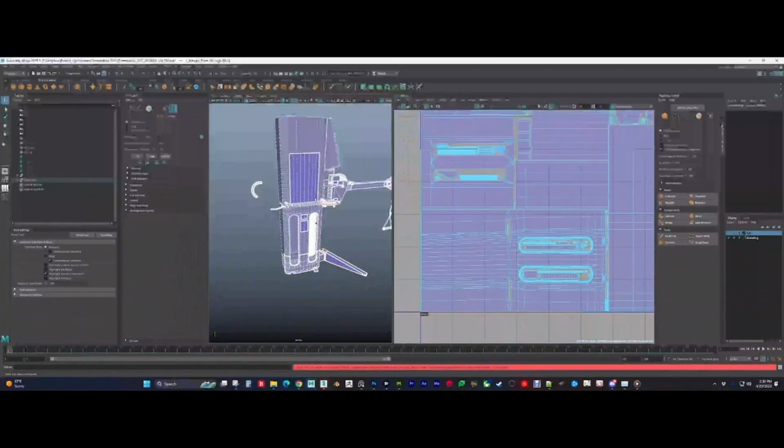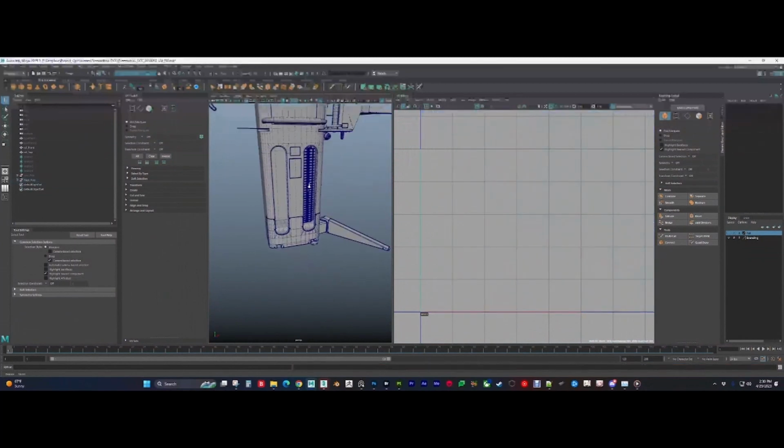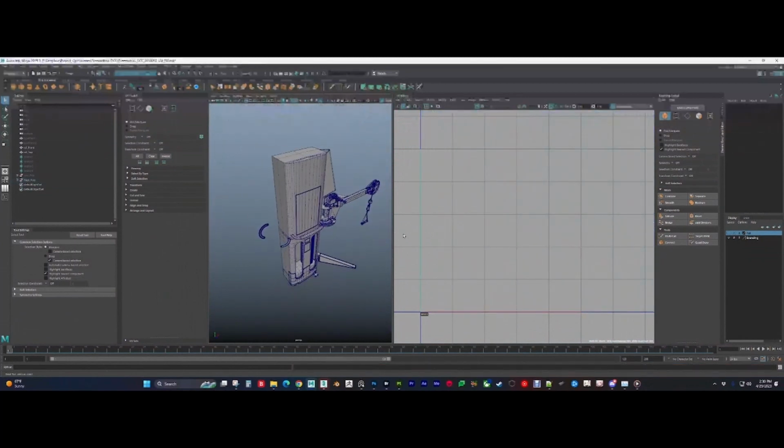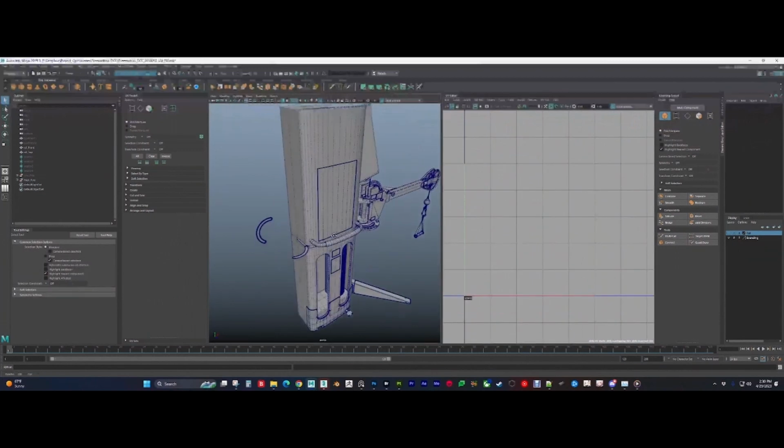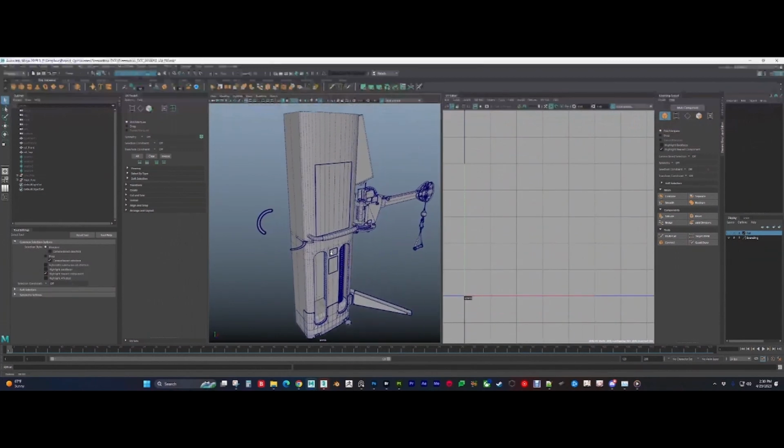And then going off into what I like to do, I use Substance Painter for my texture painting. In Substance Painter, I don't know if you noticed, but inside of the Baker, there's an option for your high poly and your low poly, and it uses a suffix, underscore low, underscore high. So I go through my model and apply the underscore low suffix to my low poly. I just want to show you how I go about doing that.